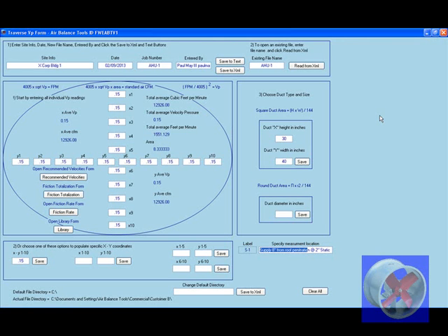So now if we came up to this air handler, we knew the reading was typically about 0.15 or somewhere in that vicinity. And we came up to the duct and we saw 0.05. We just lost quite a bit of CFM. And this could be due to a number of reasons. Could be broken duct, could be something like a belt slipping or motor speed, could be a variety of things, something blocking the entry of the fan or the inlet of the fan.